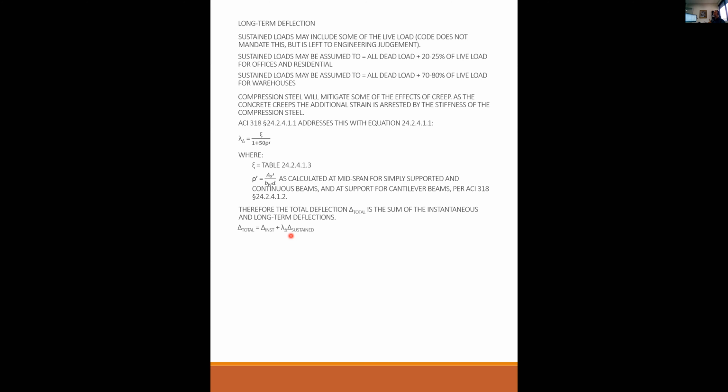So 1 inch with just dead load, 1.5 inches with dead load plus live load. And you say, all right, that's fine. I can live with that. And you pack up and you go away. 5 years later, you come back to your building and say, I'm going to measure it, just see how it's doing after 5 years. And you measure it off hours. You don't want students being alarmed with you measuring that beam. And so you measure the beam with nobody in the room. And now you see 5 years later that the beam has 2 inches of deflection with just the dead load, okay?